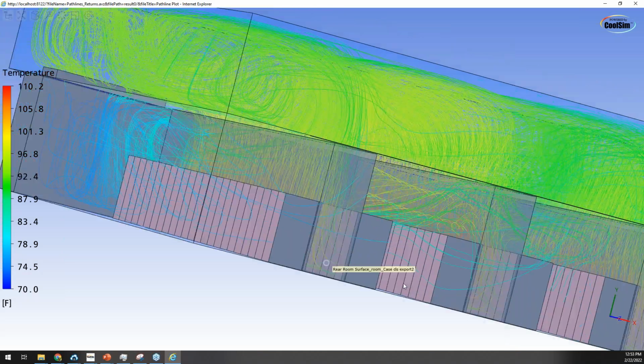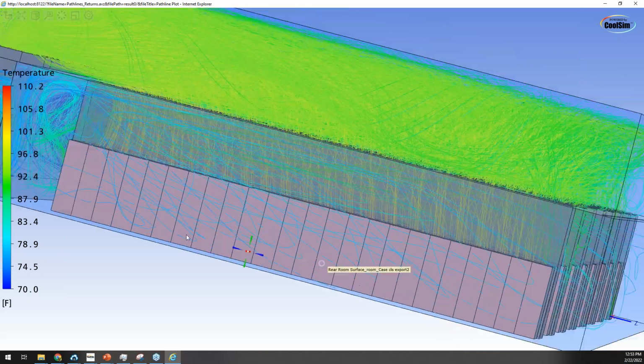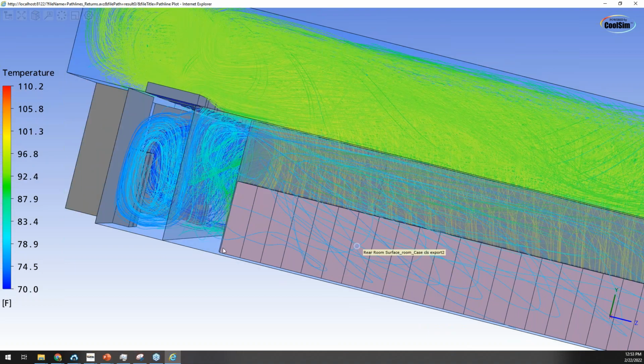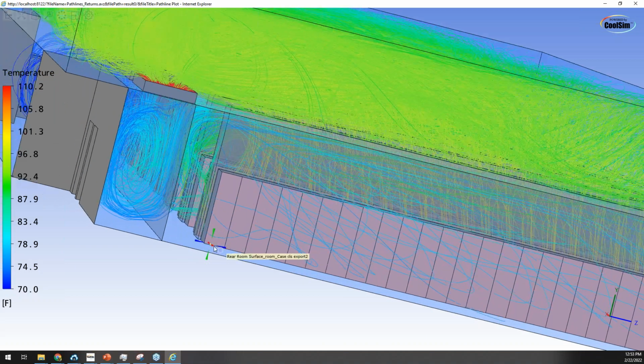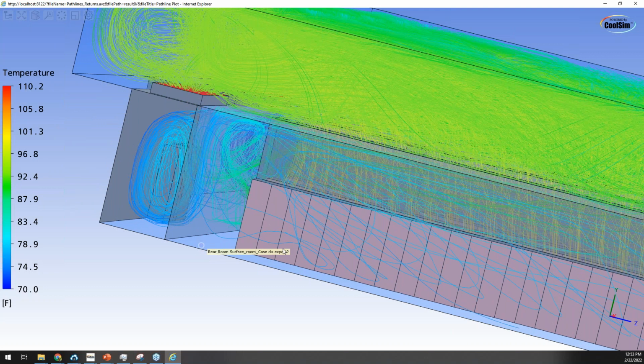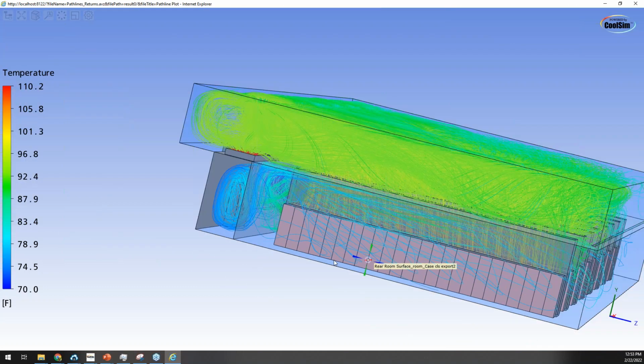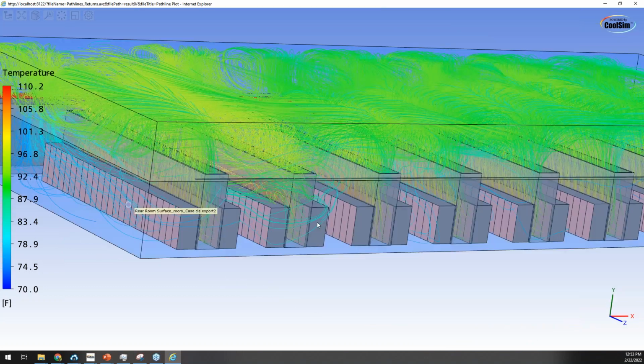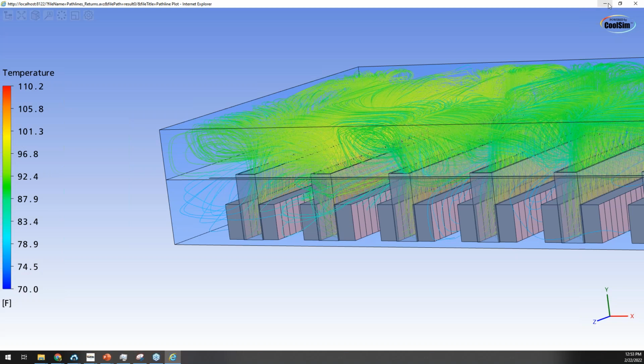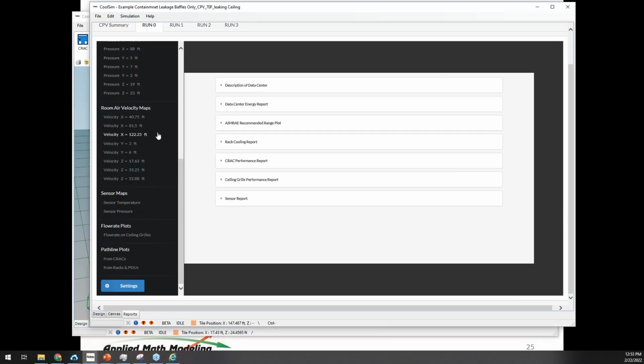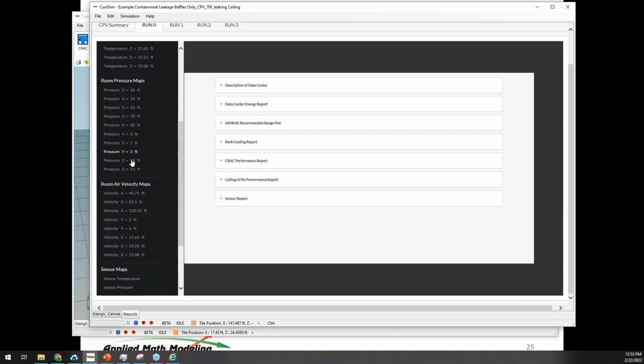This is one of the models that I was looking at that is uniform in its rack structure, but you see it's leaking out of the containment and has nowhere to go. So we've lost the pressure gradient. I don't know if I have a pressure gradient up in the ceiling. I probably don't, but you can put one up there. I have a pressure of 7, probably not high enough, but we could change that.